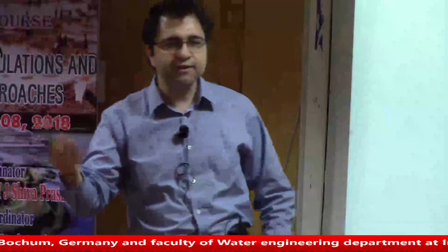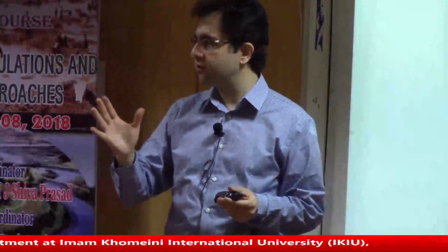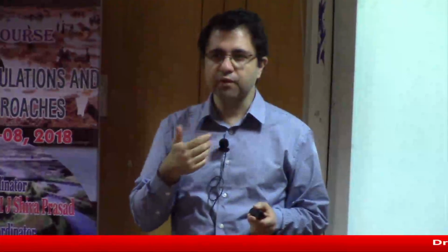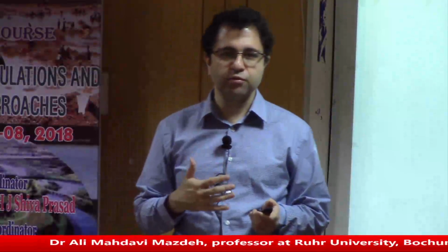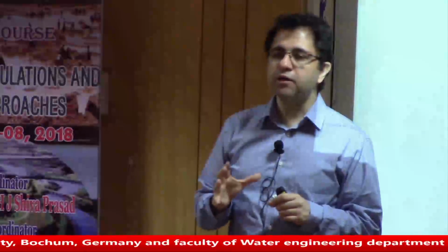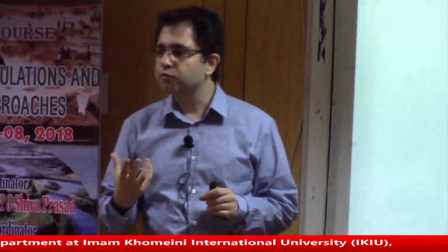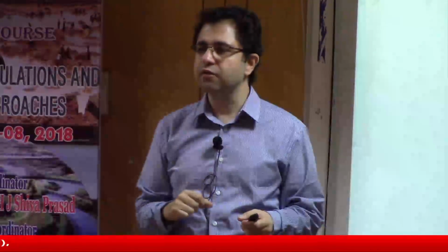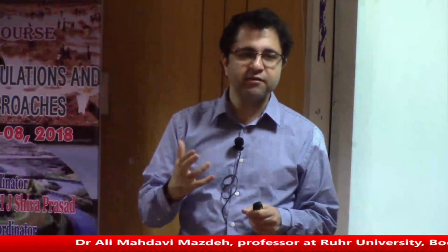Before we go to other things, when you develop your code and write your code, at first for a numerical model like an industrial one, we don't need to do this, because they did this before and they are validated and we know that they are working well. But if you develop a numerical model yourself, first you should check if it is working correctly or not. You will give some examples and see if the results are reasonable or not, and in some certain cases whether you have a valid result or not.